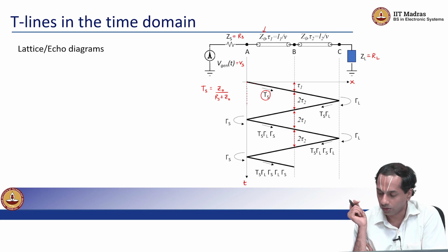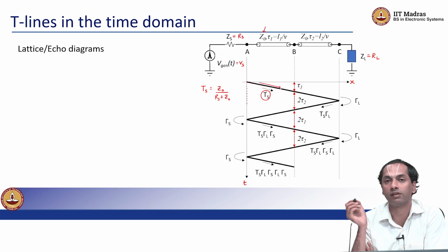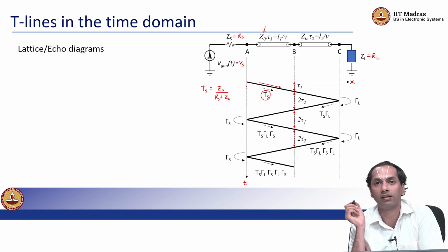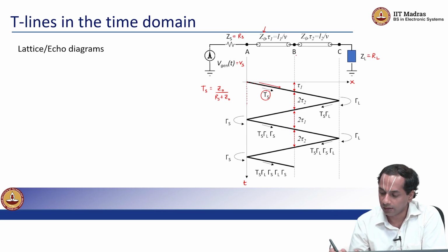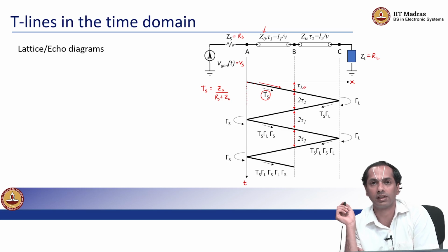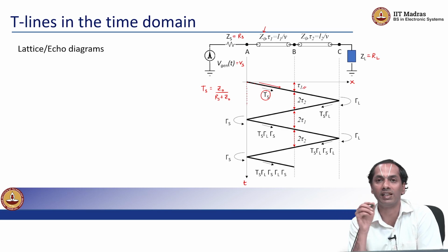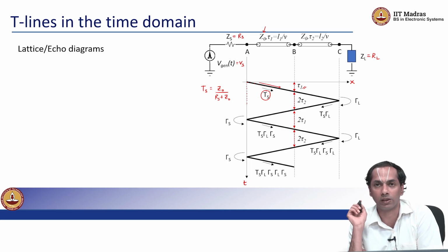Okay. So, we are noticing that the voltage slowly moves to the right, right, and it takes certain delays, right. So, if I were to look at some particular point in the middle of the transmission line B, I will notice that it takes time tau 1 to reach there, right. So, let us assume for simplicity that this Vs is just a pulse, right, a short pulse of say 1 volt, right, and I am launching this 1 volt at time t equals 0.